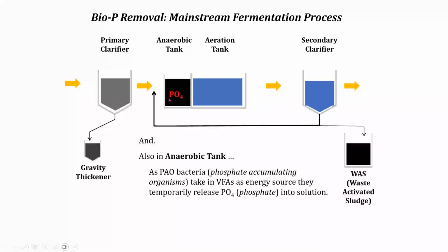We've got anaerobic digestion going on. We've got cells dying and releasing more phosphorus into the solution than we want. So there's a window in there of what is optimal. So there's a process control tool. If we measure the soluble phosphorus leaving this anaerobic tank, entering the aeration tank, and compare it to the soluble phosphorus coming in, we're looking for a 3-to-1 ratio.